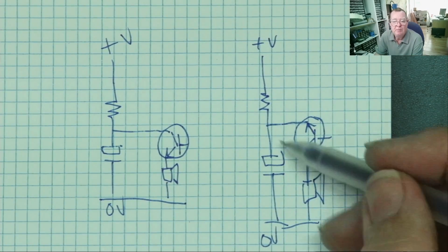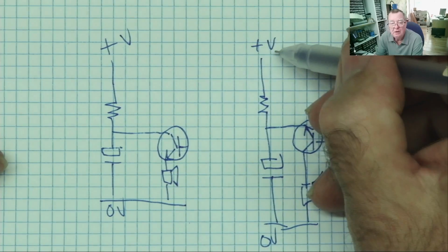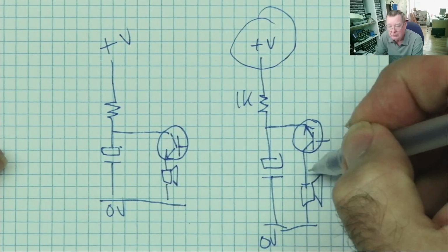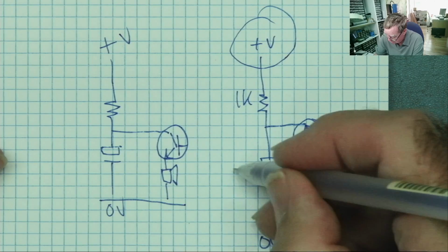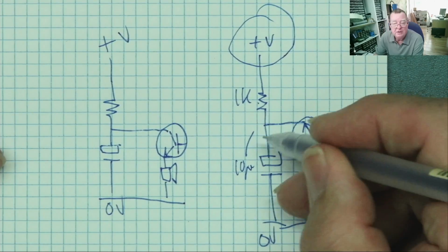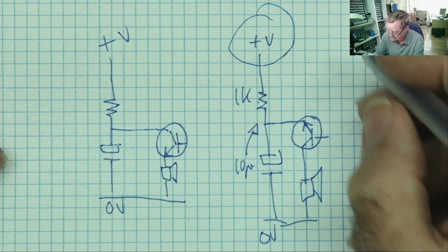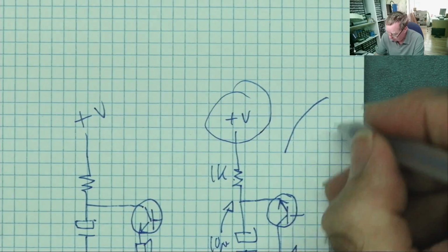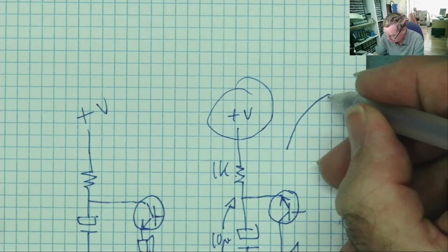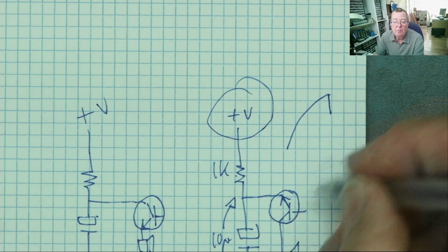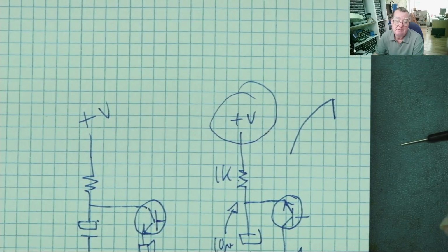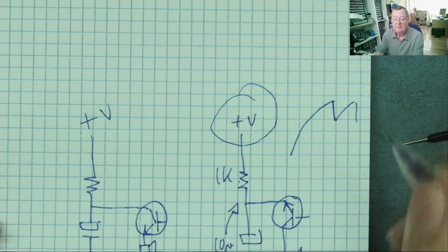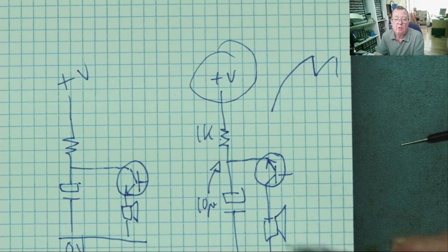But it can only withstand the voltage to a certain point. When you reach enough voltage here, then current will flow through the transistor. And that happens when this capacitor charges up via the 1K to a sufficient voltage, the curve I just showed you. Now the transistor breaks down. But once it breaks down, it starts to discharge this capacitor. The voltage suddenly drops, and when it reaches a voltage below, you've seen about 10.8, the transistor stops conducting. And so the capacitor charges up again. And that's why it makes a noise on the speaker in one direction.